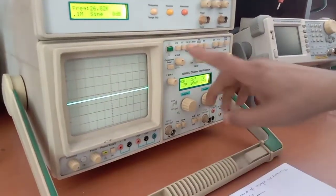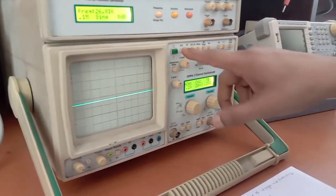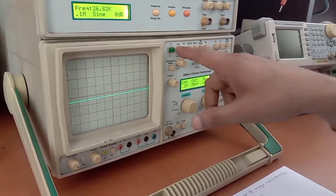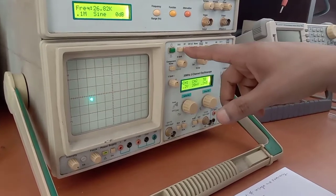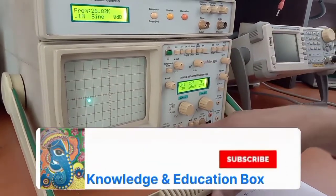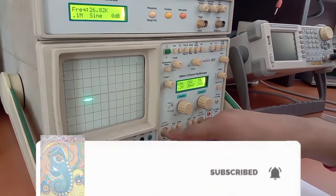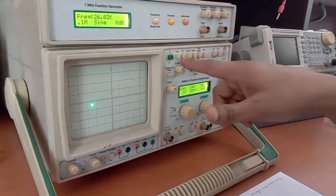So this button is to reduce the signal frequency to 10 times. We will see shortly. When we press this button, the internal time generator will be detached and we will provide the two independent signal waveforms externally. This is used to plot the Lissajous pattern. We will see later on.